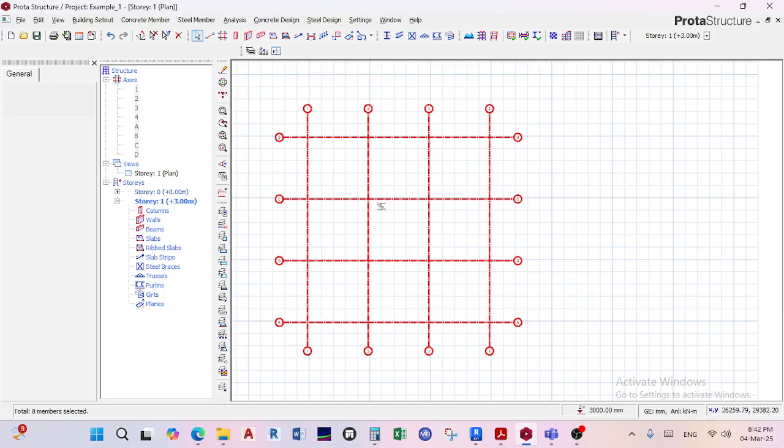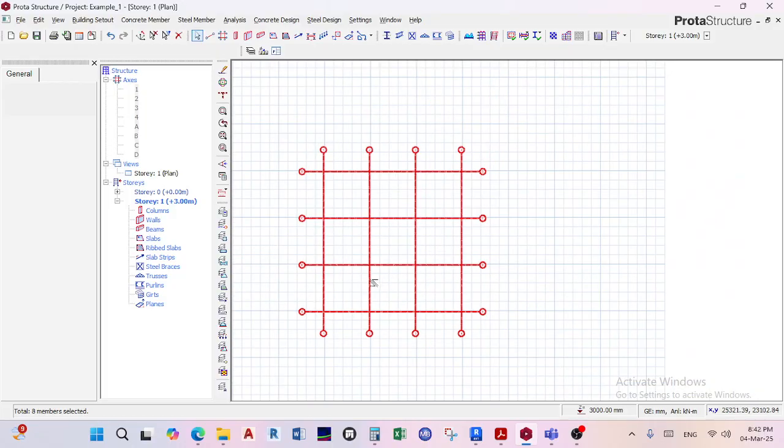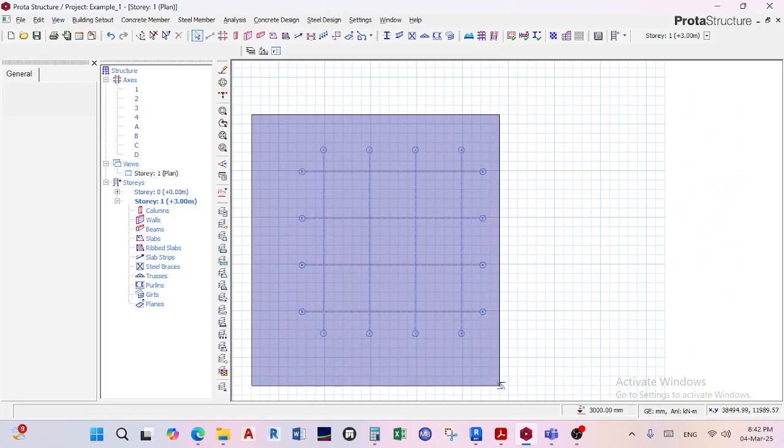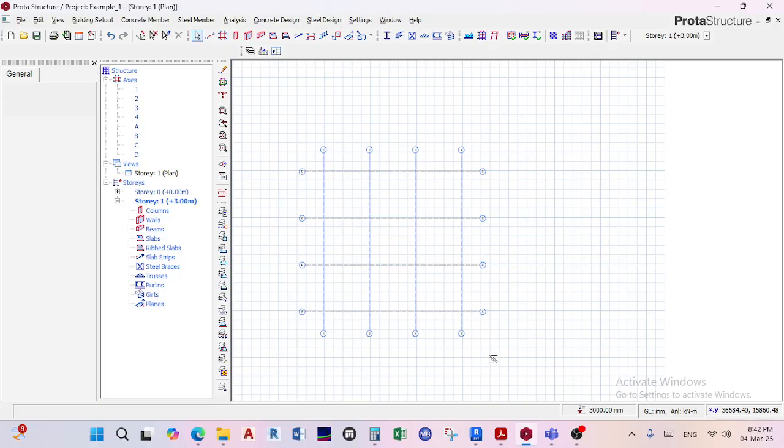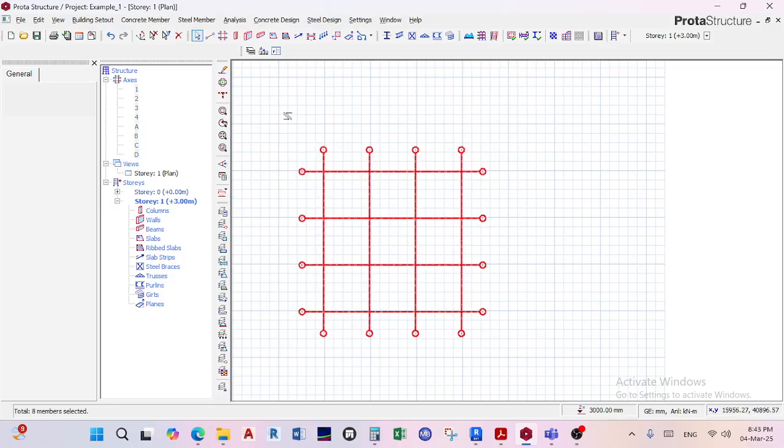You'll be selecting everything that's within that box that you created like that. But if you start from here, similar to AutoCAD, you can only select whatever will be completely covered. For example, here, only these were completely covered. The ones at the top weren't. So when you do that, now everything is covered, right? So I'll delete that, okay?